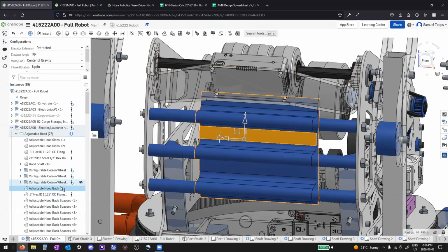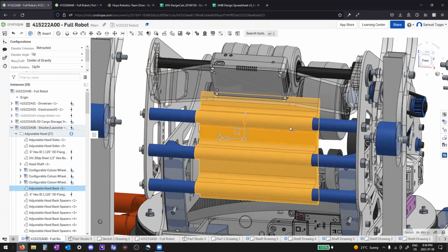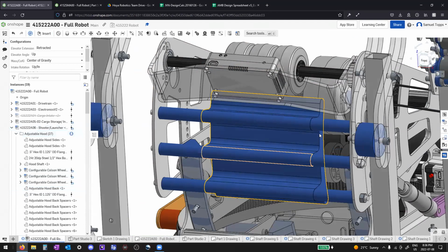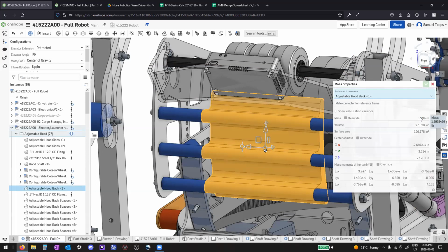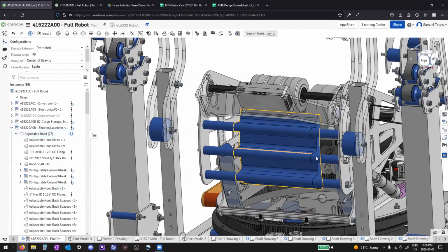And a little part like this has infill in it. I don't know what infill we were using. It's pretty low actually, like 27 or 30% infill. So a whole bunch of the inside of this piece is actually hollow, and this thing weighs almost nothing. If it was solid, it'd weigh 1.3 pounds, but right now it weighs like a third of a pound or something.